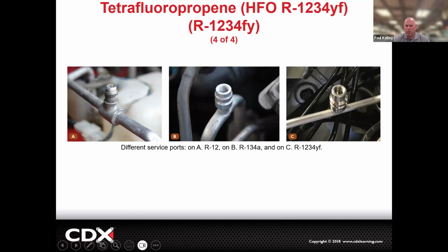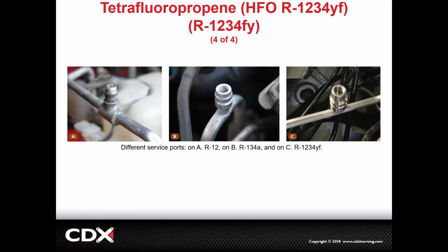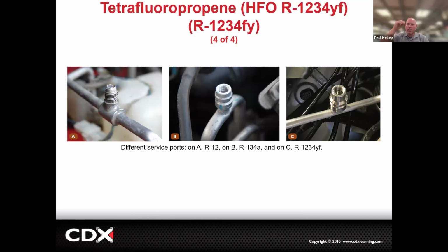David, you can go ahead and ask your question. Go ahead. I saw that pop up. This is all to prevent cross contamination and ruining systems and whatnot. Exactly. We can't have this refrigerant mixed with that refrigerant, this oil mixed with that oil. They're not compatible. The main concern is the R12 oil with the R134A oil. That creates the hazardous gas. It'll corrode and cause damage. So it's all exactly what you said, to prevent cross contamination.